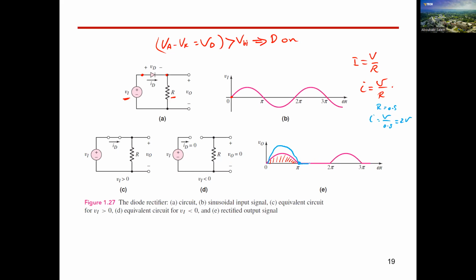So you don't have any volt across this resistance, because 0 times R equals 0. So the volt will be 0 at this interval until the supply turns positive again, and it will move again in the same shape. So this is, guys, I of omega t. Omega t, because here we have this axis of omega t angle; it's not only time. This is simply the operation of a diode if we apply an AC supply. If we applied a DC supply and it is forward biased, the current will flow. If it is reverse biased, the current will not flow, regardless of the value of the applied volt. Okay, so this is what we have for the part where we apply an AC supply to our diode.